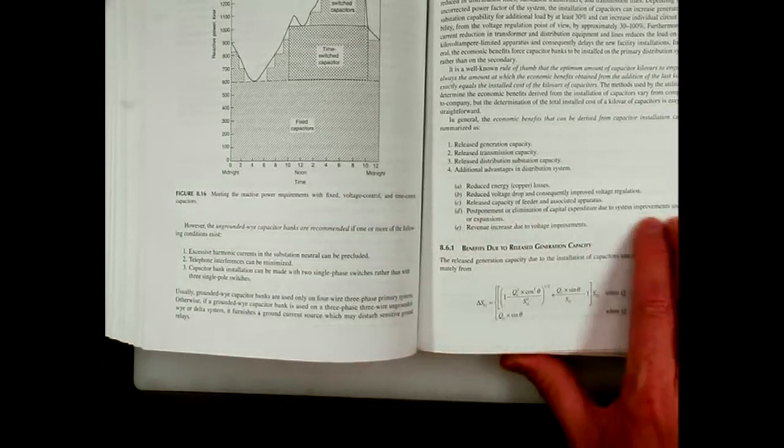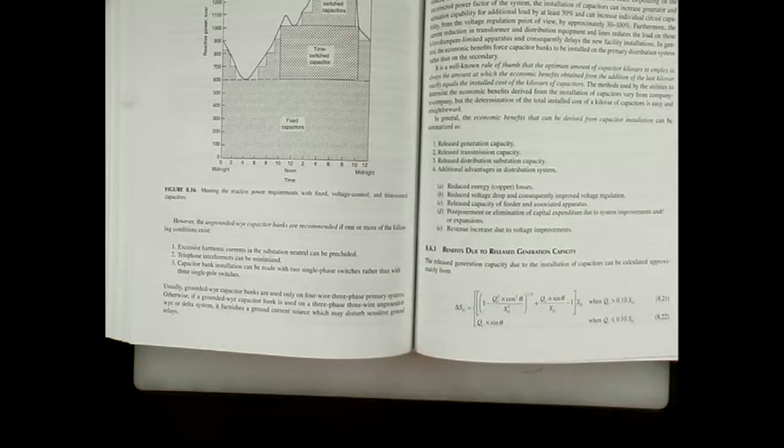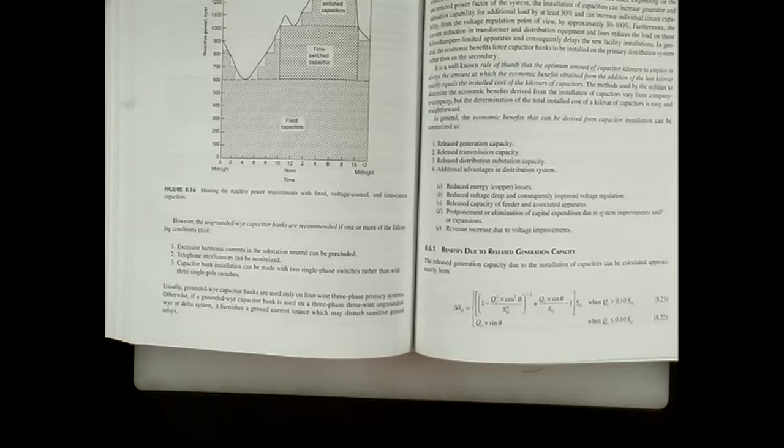Postponing or elimination of capital expenditure due to system improvements and expansion. Well, this is what they're talking about, the benefits of distributed generation. If I need 10 megavolt-amperes more in this area, because now we are going to have a Hilton on the corner, then we are going to have a shopping center, whatever, the expansion. You need to bring that power. If you have distributed generation, if you have a fuel cell that is using gas, I don't need to bring the power inside the area because I can generate 10 megawatts using this fuel cell. That's distributed generation. So that means that I don't need to install another power transformer at the substation. I don't need to upgrade.